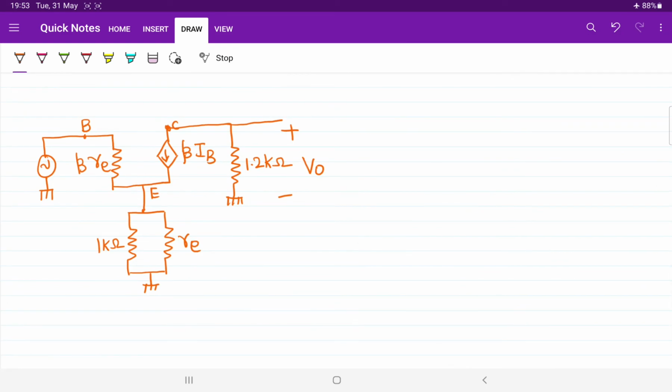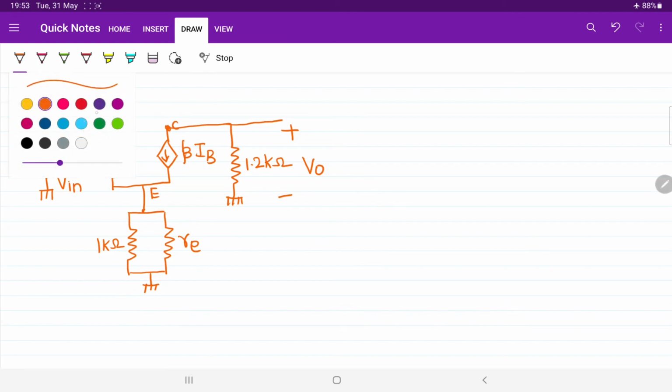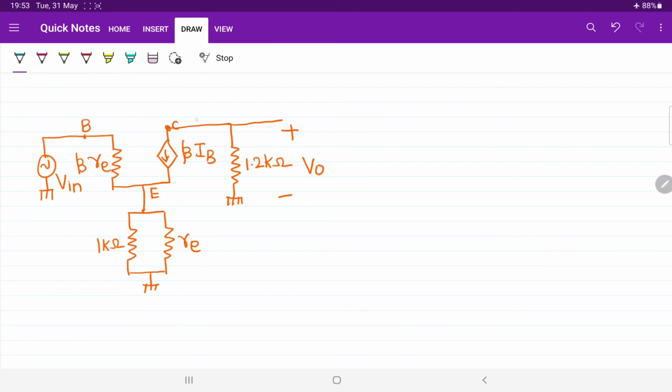Now I hope you all understood till this point. What is the question, sir? The question is: what is the voltage gain of the circuit? I have already delivered 2 lectures. If you understand this pattern clearly, there is nothing more you need to do. Just apply common sense to whatever we observed. This is the collector terminal; externally, collector current will go here. This is the base terminal, base current will go here, NPN transistor. This is the emitter terminal, emitter current will go here according to DC analysis. You don't need to do anything else: replace the transistor by its equivalent AC, that's all. After that you can consider all other parameters as they are.